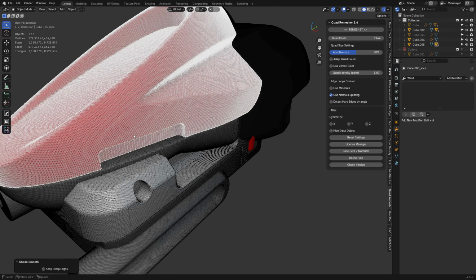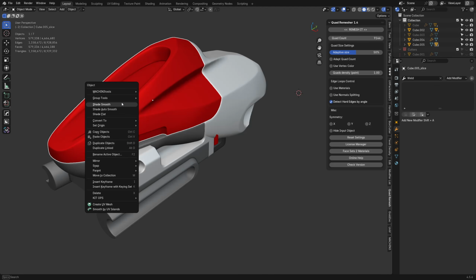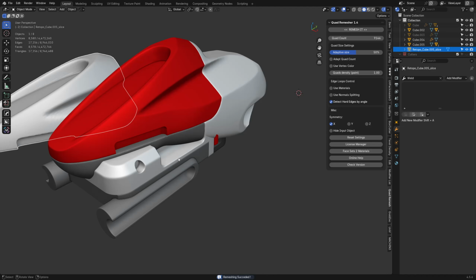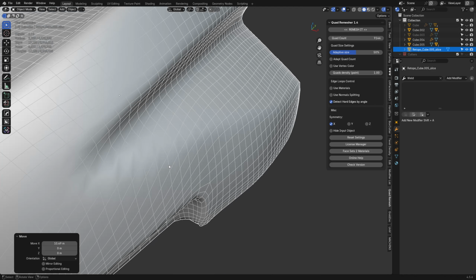Because I'm pretty sure, as long as you smooth them down a little bit, Quad Remesher, using just a normal setup here with shade smooth, no sharps on it, uncheck sharps, and symmetry if needed, will remesh a lot of this with the voxel setup. But it's oftentimes slow to get going, and you might have to decimate it first. And B, it tends to do this right here.